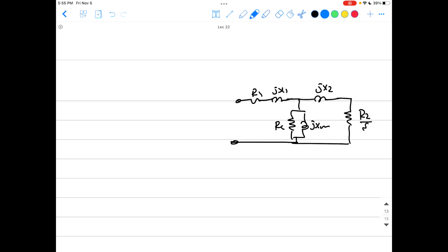Okay, under the no-load condition, you know for yourself that Nm is less than the synchronous speed. The machine rotates at less than synchronous speed, but Nm is very close to Ns. You remember this from before. So Nm is very, very close to the synchronous speed, and with the increase in the load, Nm starts reducing.